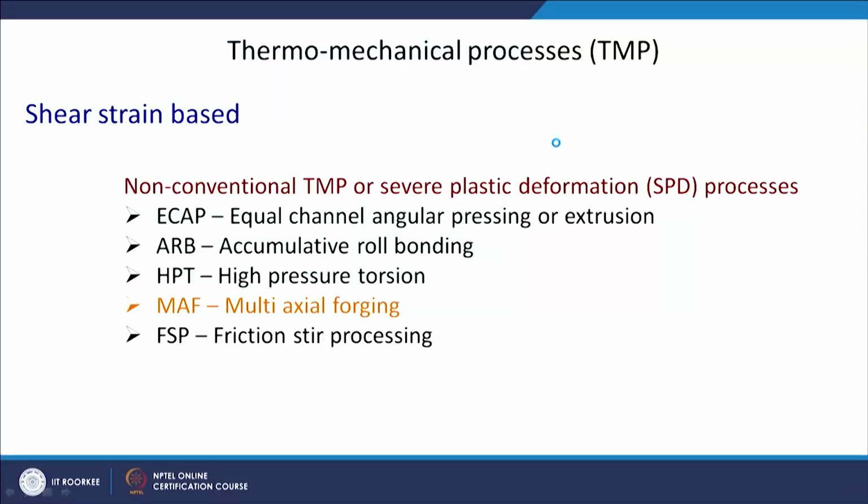There is another category which is what we call non-conventional thermomechanical processing, or a more popular name is severe plastic deformation, SPD processes. These are based on shear strain. So, the deformation or the strain is imposed under shear condition.